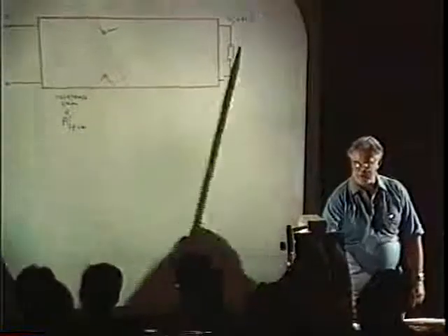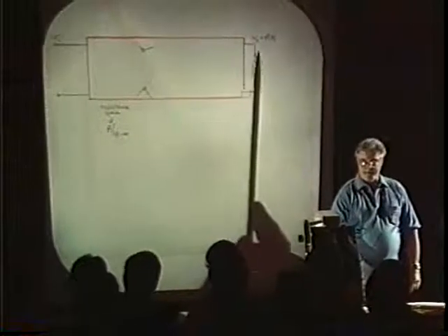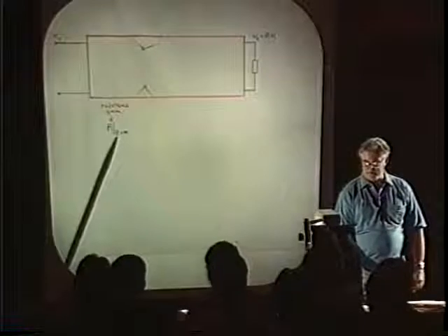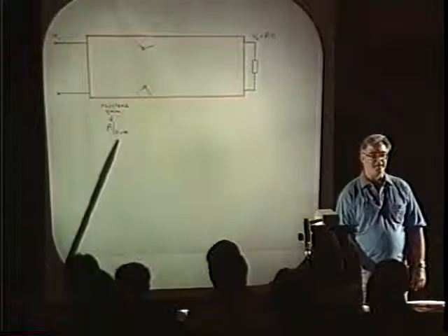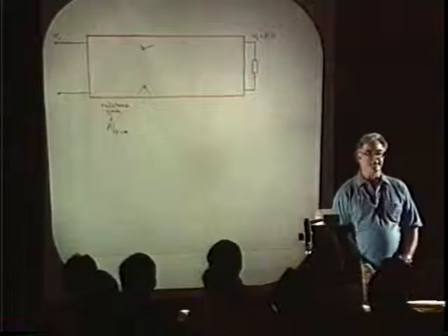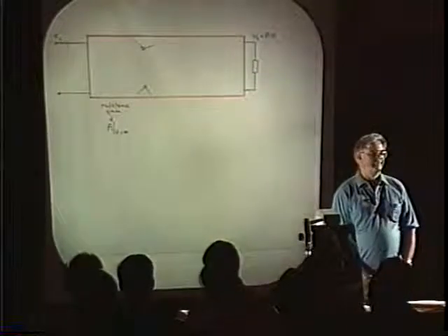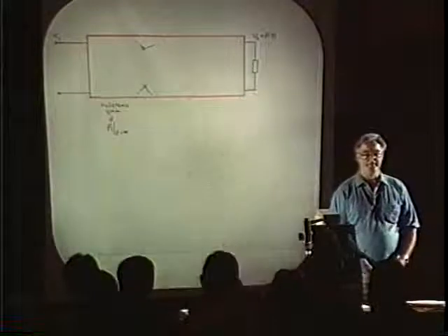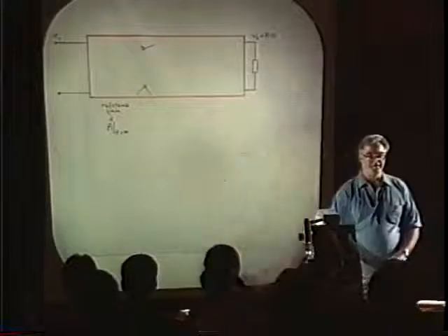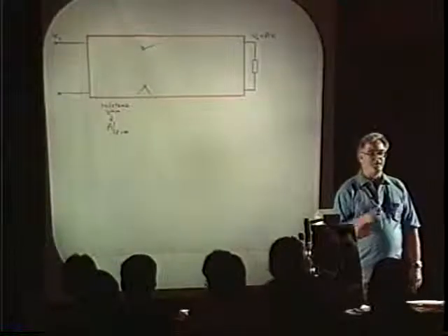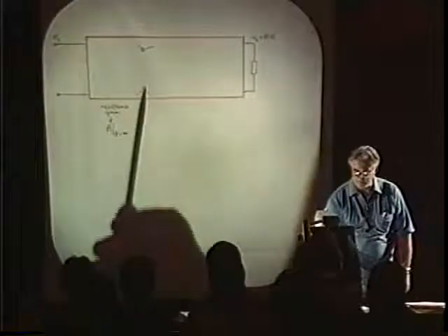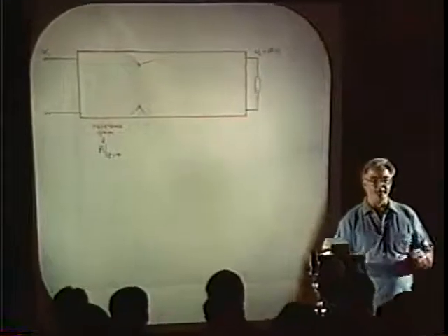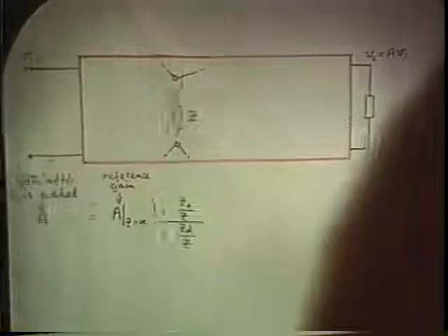Here's the circuit model you've already analyzed for the gain. That's the A. Call it the reference gain. And I put this condition z equals infinity on it, where z is the extra element, because when you do that calculation, you haven't thought of the z yet. It doesn't exist. That's the first answer that you get. So now later, as a result of the measured discrepancy or whatever, you decide you want to add a certain element z at a certain place. So you identify a node pair across which you want to add the extra element. There it is.